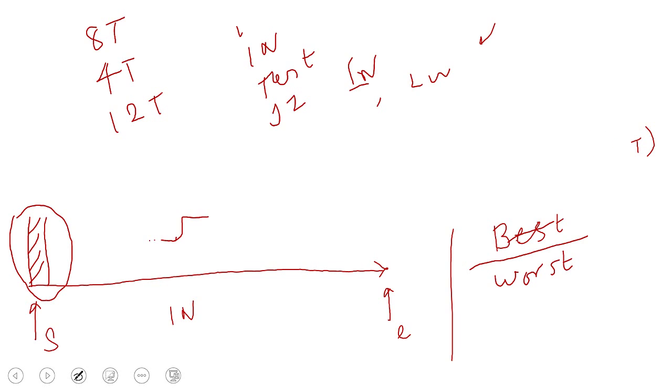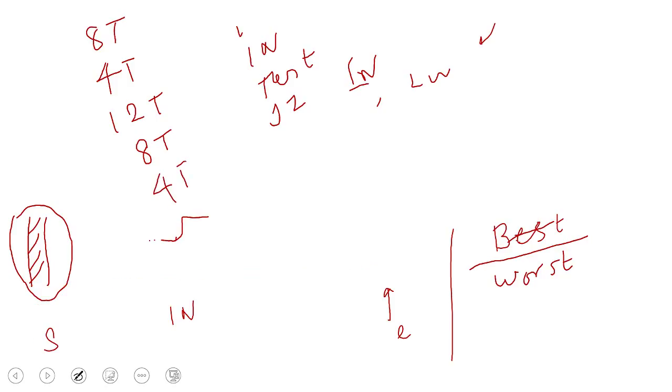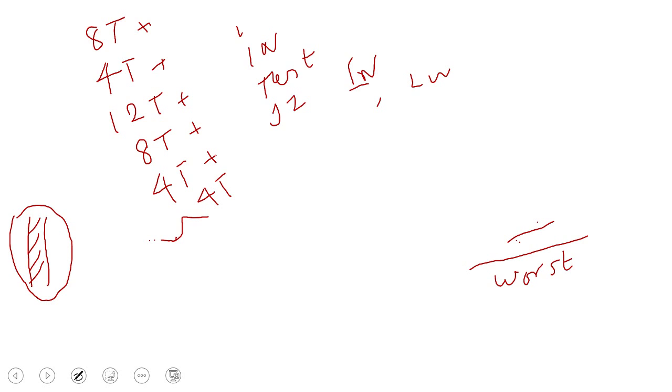But still you are waiting at the bus stop. So when the bus comes again, you will get inside whenever it's getting open. The door is open nevertheless. So next time when the in operation happens, it takes another 80 cycles, and you will do a test operation, that's 40 cycles, and jump 0, this time it is successful, so it will be just 40. So the sum of all these cycles will give you the worst time of this polling latency.